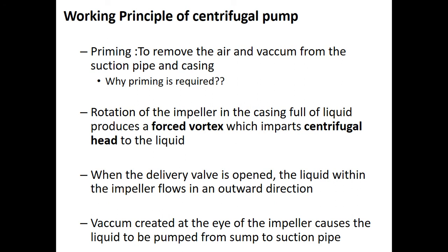Not only water, sometimes some kinds of oils are pumped using this kind of pump. So the first step is filling the suction pipe and casing with the liquid to be pumped. If it is water, that's called priming.